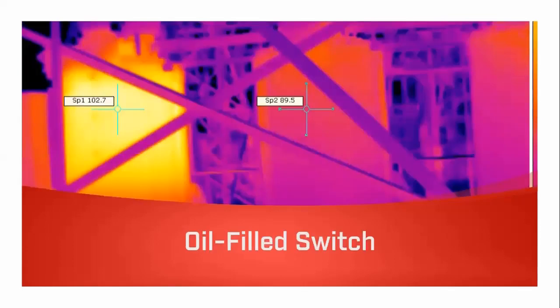We've got oil filled switches. We've seen similar ones to these. The implication with these is that the heat inside these units and what's displayed on the exterior is quite different. There is some guidance that 3 to 5 degrees C difference measured on the outside is enough to take this out of service. My caution is that the indirect differences on these large substation components should be taken quite seriously.